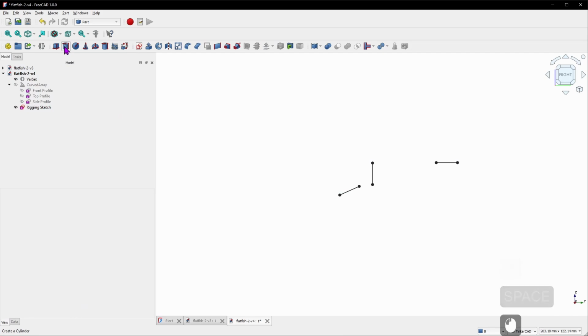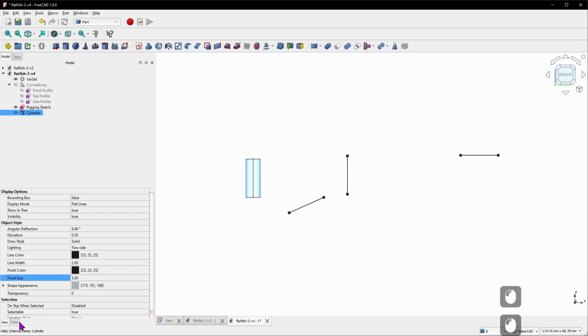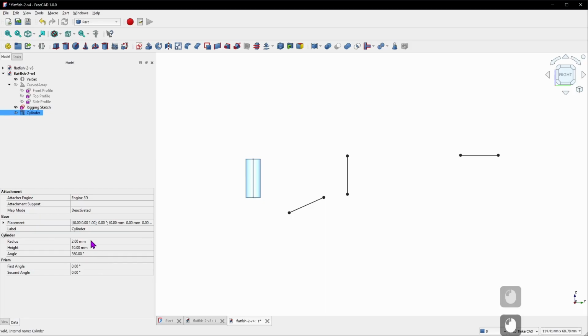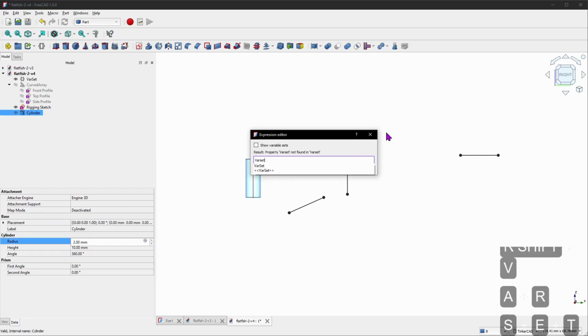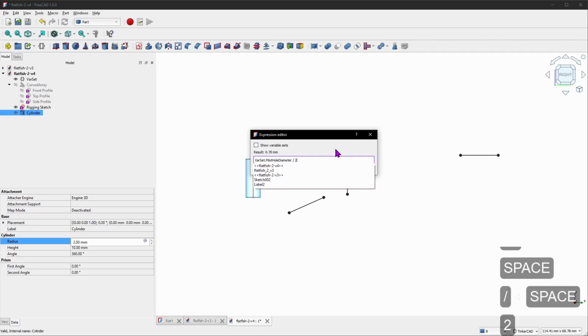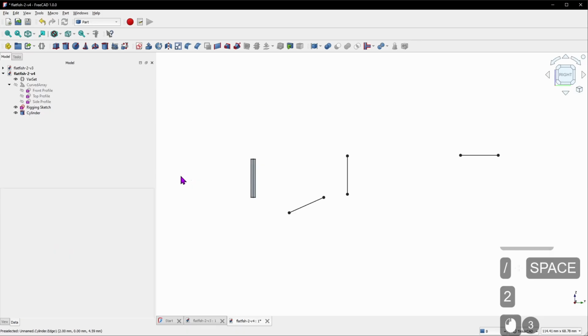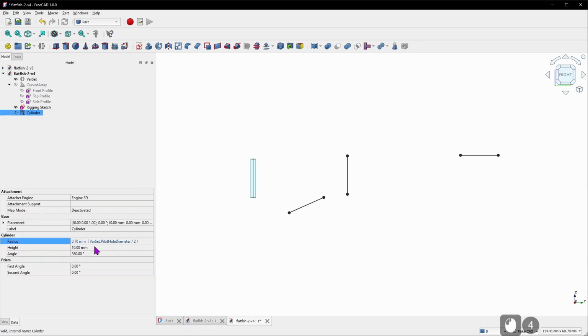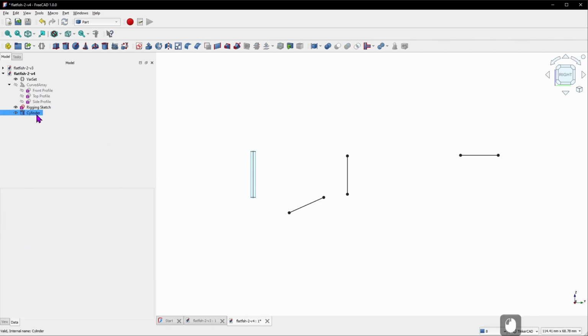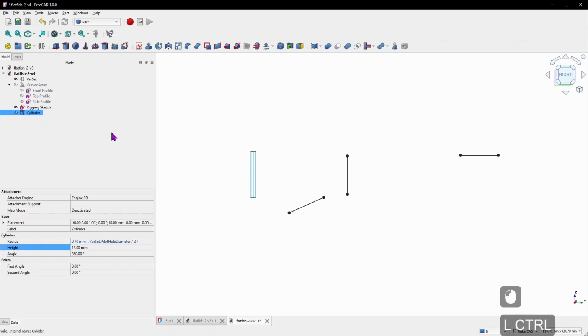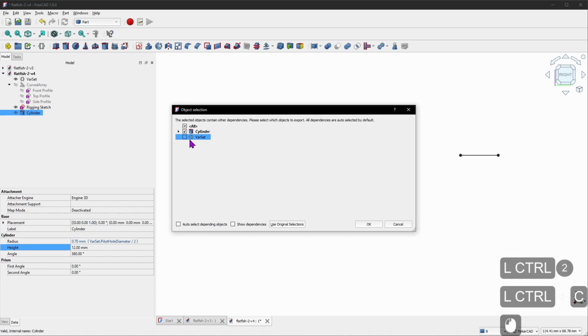Let's drop a cylinder from the primitives up here. And for this cylinder, if we go to its data tab, I would like that radius to match the pilot hole diameter and divide it by 2 since it's a radius. And then for its length, I'm going to set it to 12. Now I'm going to select that cylinder and hit Control-C on my keyboard and deselect the varset.